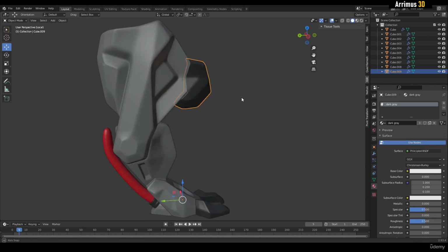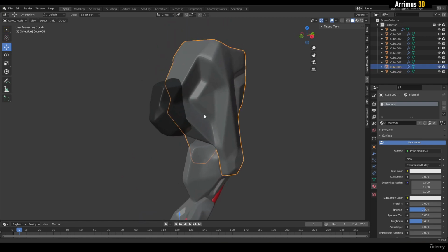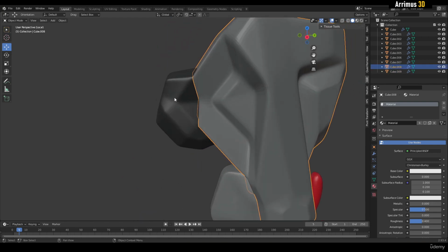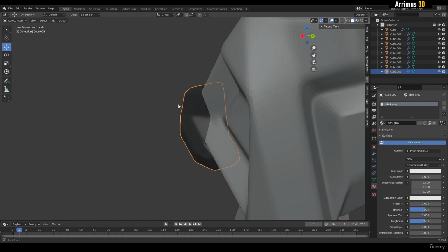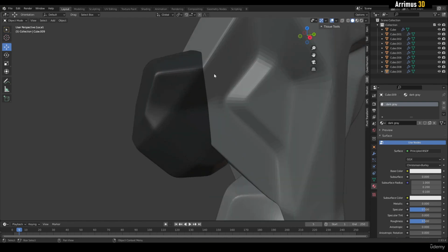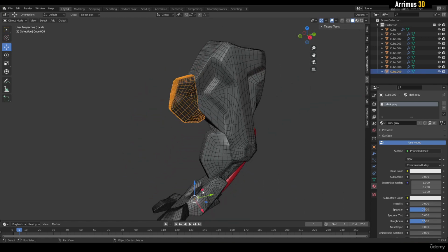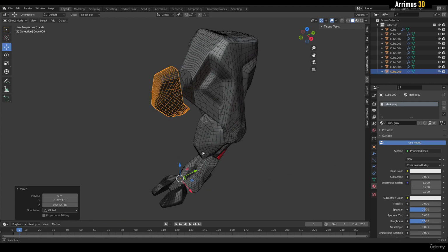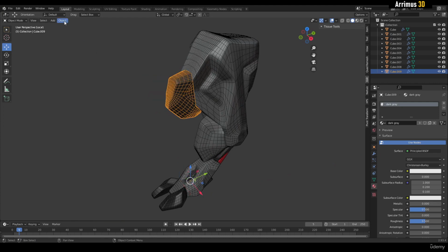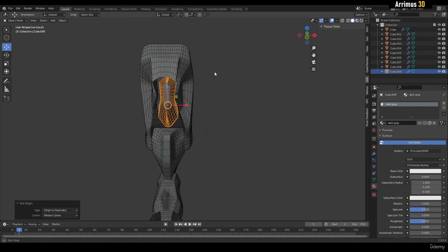So this could be like some sort of, I don't know, armored kneecap detail. All right. Probably do want to cap the back of this, because one thing that makes designs more interesting is when things capture highlights. You can see because I just ripped this off here. In fact, at this point, it may be a good idea to center that. So we can go to Object, Set Origin, Origin to Geometry. That's going to move the origin right here.